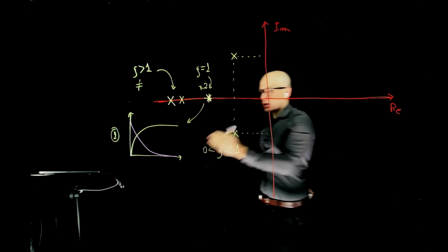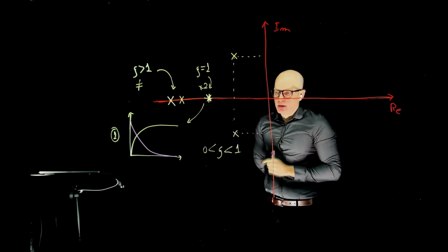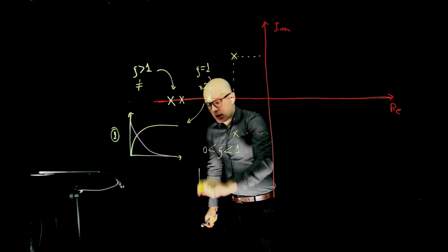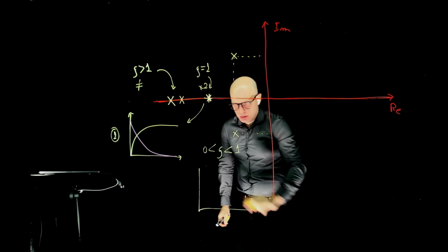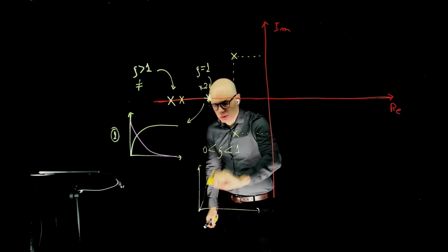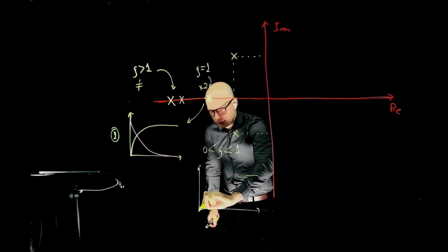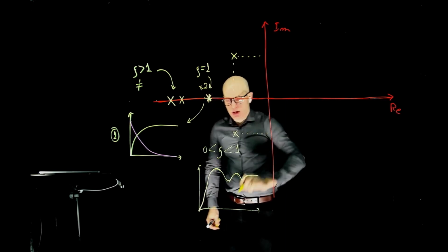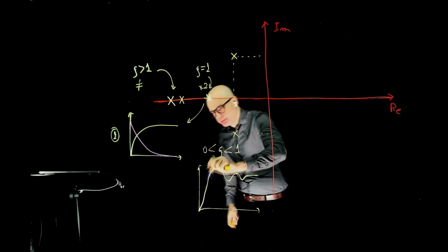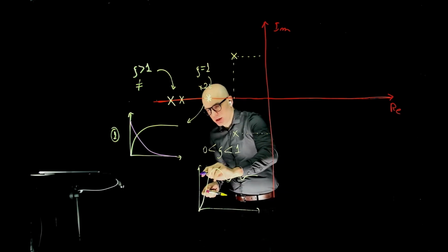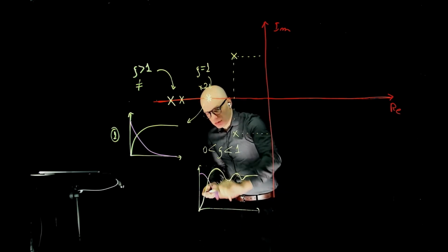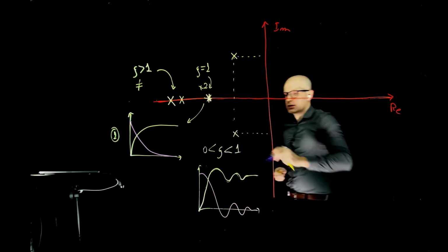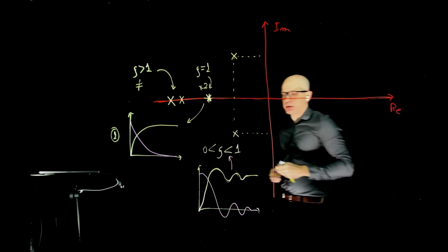It still lies on the left side of the S-plane, meaning that their exponentials will die to 0. And the time response for a step input will now have both sinusoidal and exponential components, like that. And the time response for an impulse will be something like this. Now this will be the third case there.